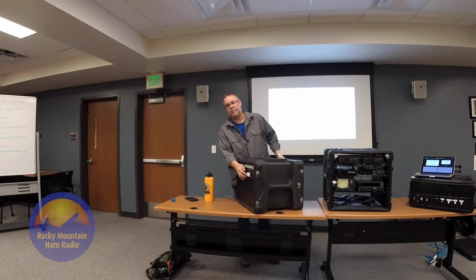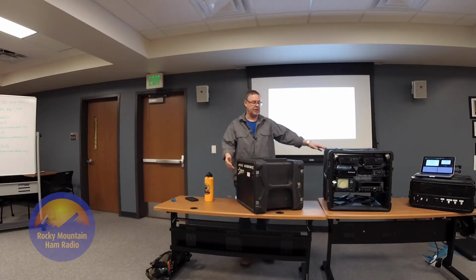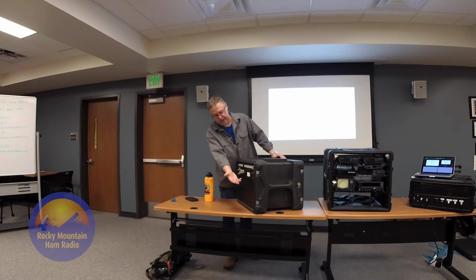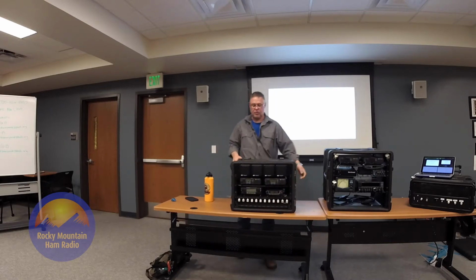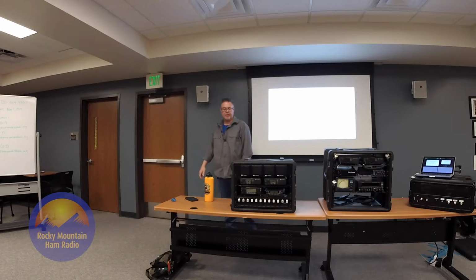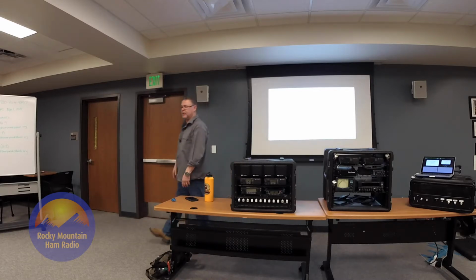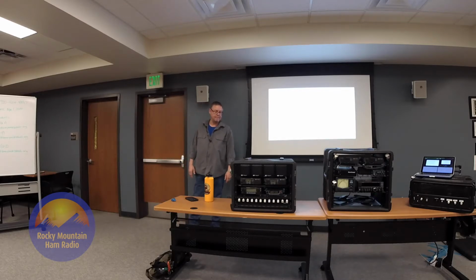External power, I can supply power to someone else, a light, another box like John's box. If we forget the power strip, he can plug into me and I can provide him power. It's switched power. All my 110 on this thing is switched by this switch right here. So if I turn that switch off, not only does the 12 volts get killed from the power supply, but all my external power gets shut off. And it was built more of a safety feature, what I thought would be a safety feature, but it really hasn't turned out to be necessary.